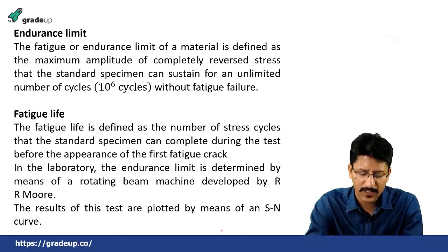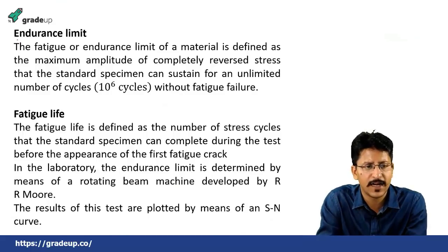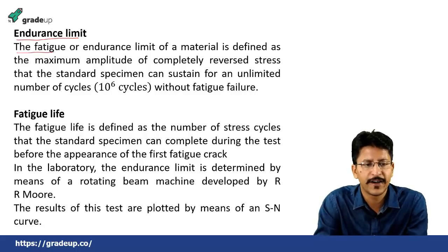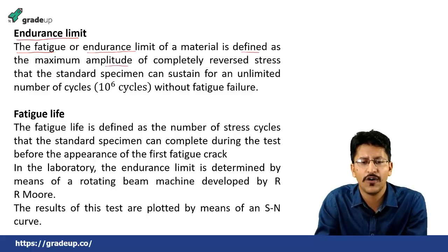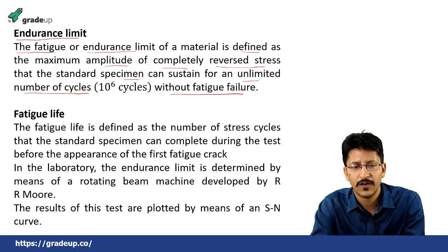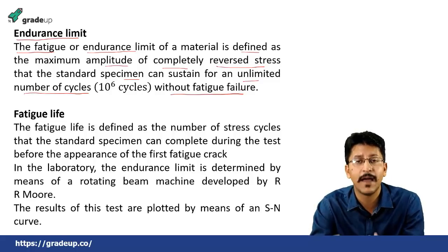Then, for this case, there comes a term that is known as endurance limit. The fatigue or endurance limit of a material is defined as the maximum amplitude of completely reversed stress that the standard specimen can sustain for an unlimited number of cycles without fatigue failure. So it is the maximum amplitude of the completely reversed stress.